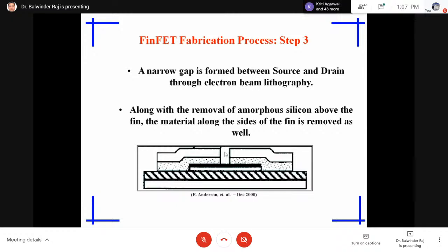If we are using a wet etching process, we use some chemicals, hydrofluoric acid, and sometimes diluted or concentrated. For etching we use a concentrated one. So hydrofluoric acid type of etching, as its name suggests, is very chemical, so we know it as wet etching, and here the precise control of dimensions is not possible. So in dry etching, where we use some applied voltage, we can say precisely the dimensions can be controlled, and we can remove this cut.